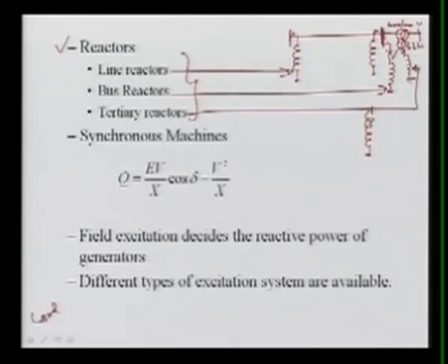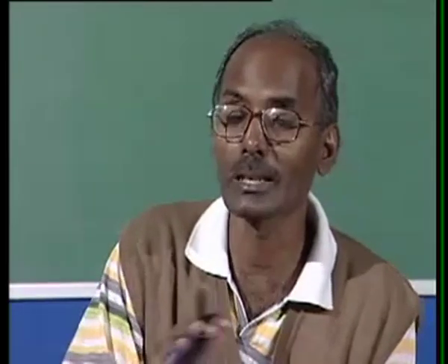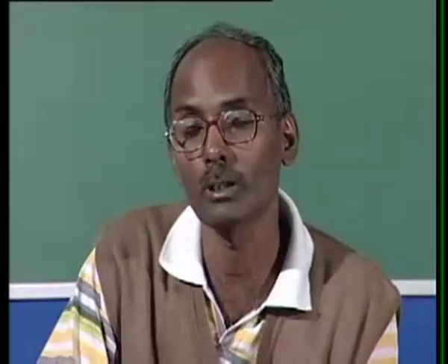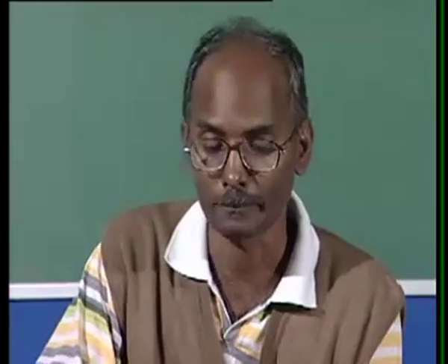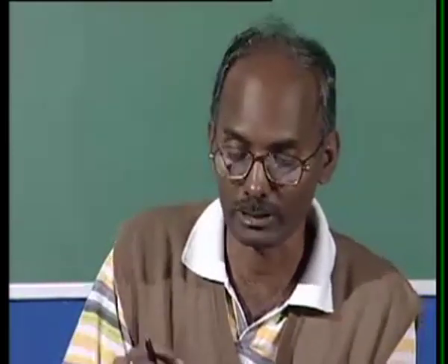So these bus reactors and their tertiary winding reactors are used especially in the overloaded condition. But the line reactors are permanently connected in the lines. Whenever the line is energized, it will be connected. It is immaterial what the loading of the system is.